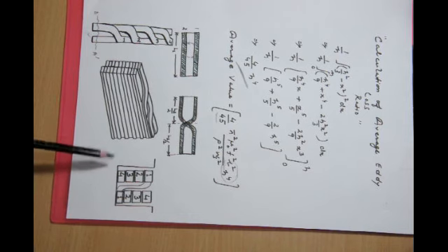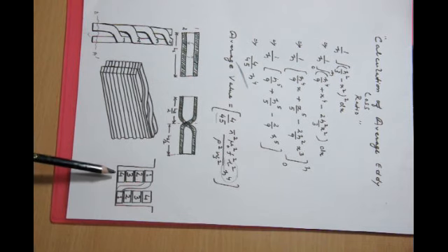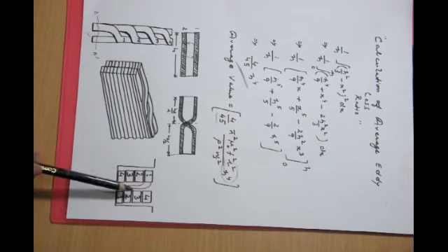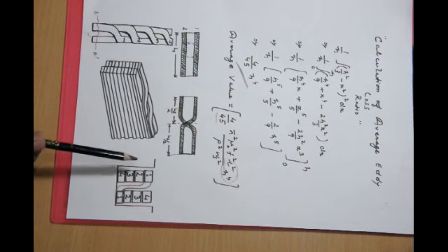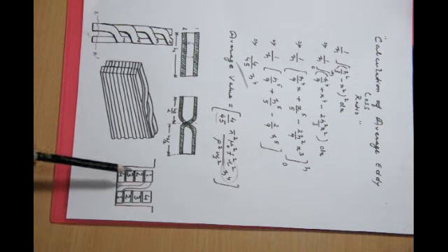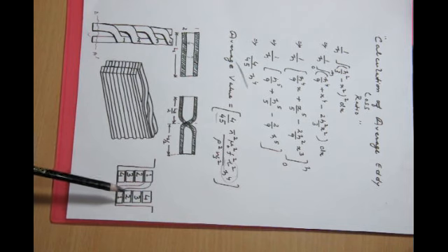So what will happen is the difference between conductor 1 and conductor 4 would be minimum. Similarly, the difference between conductor 2 and conductor 3 would be minimum. So to a greater extent we have eliminated the eddy current loops. To a greater extent we have minimized the losses.